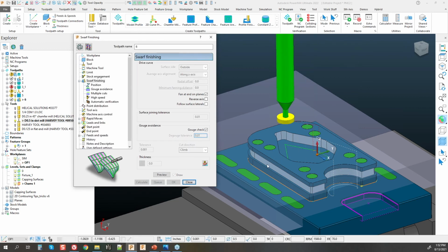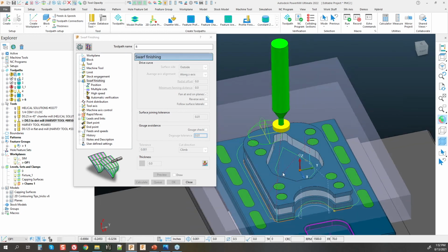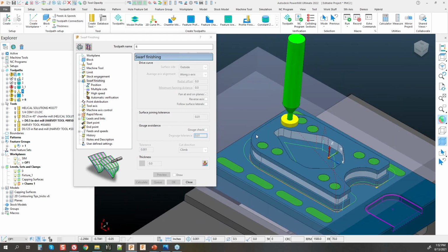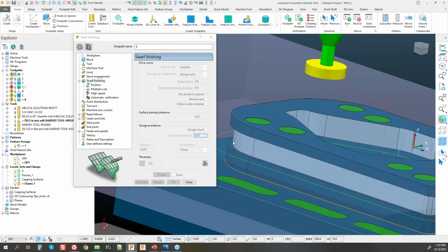Now, gouge is also taking place here. So this is an instance with an undercut. I might come in and untick gouge just to calculate, to make sure I get a preview of the toolpath, see what it's going to do. You'll see that I get the successful swarf toolpath all the way around it. But that's a 2D feature being machined with our swarf toolpath.